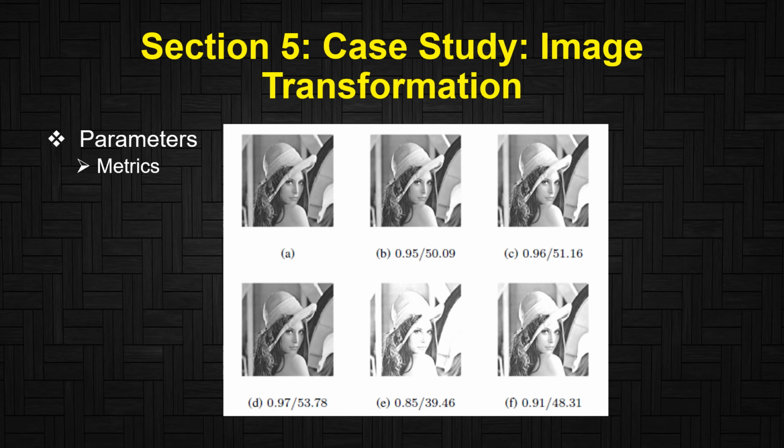As we can see, RAD256 has the worst quality, R4ABM1 has the best quality because it has a smaller SSIM. The proposed approximate Booth multipliers achieve a PSNR close to 50 decibels, but HLR-BM2 had a better PSNR as compared to HLR-BM1.